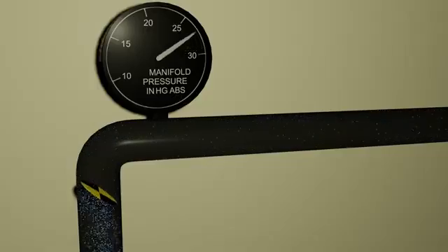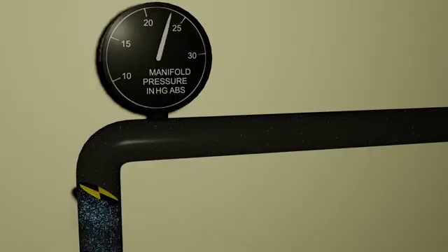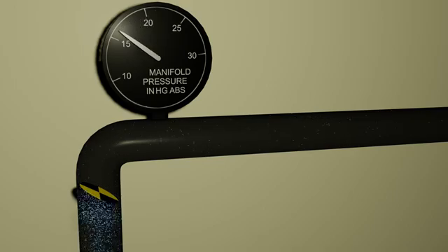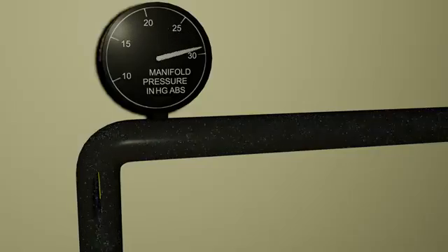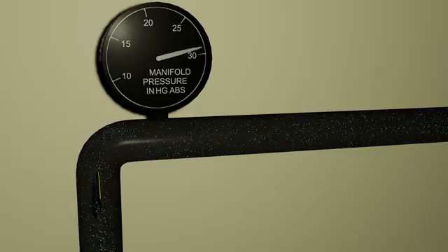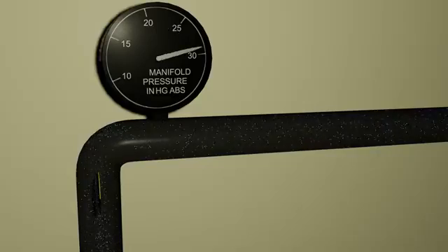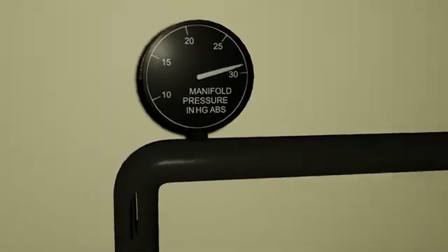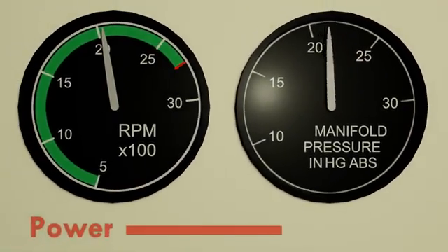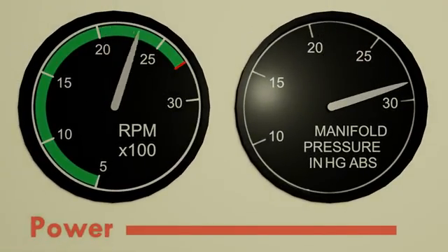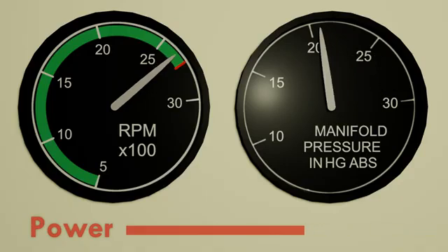As we close the throttle plate, we start constricting the engine. The manifold pressure decreases from its maximum of 29.92. Why 29.92? Because at full throttle, the restrictions are lifted, so the engine can draw maximum atmospheric pressure. And what's atmospheric pressure at sea level? 29.92 inches of mercury. Each of the manifold pressure and tachometer can't tell you the power individually. Only by looking at them together can we have a sense for what the engine is doing.